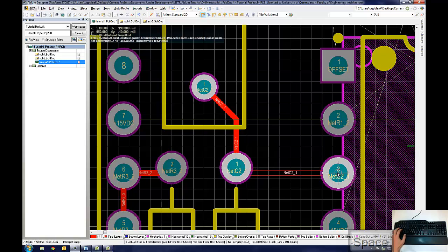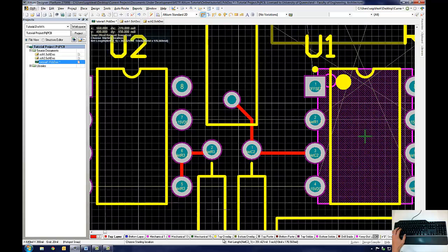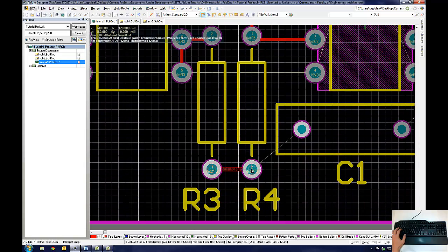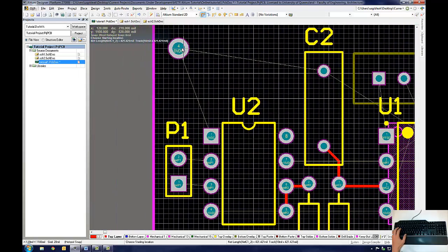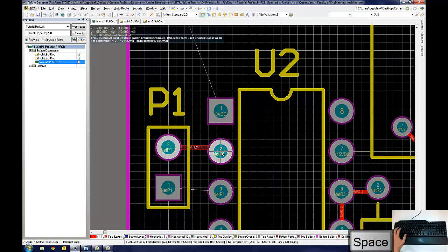If the direction is not what the user desires, then they can change it by pressing the spacebar on the keyboard. The user will notice that the grey line directly connecting the 2 points will shorten as the track gets closer to its destination. The user can click on the PCB anytime they wish to change the direction of the track. This establishes a waypoint in a very similar fashion as placing a wire on the schematic document.